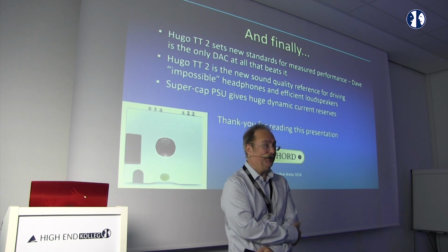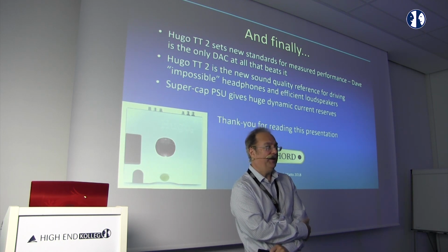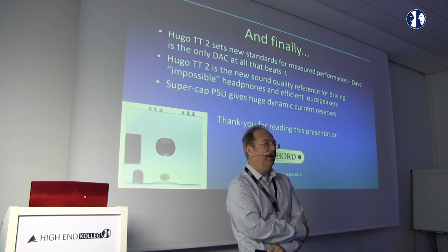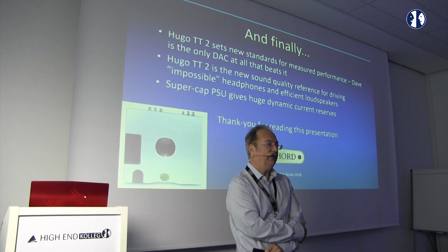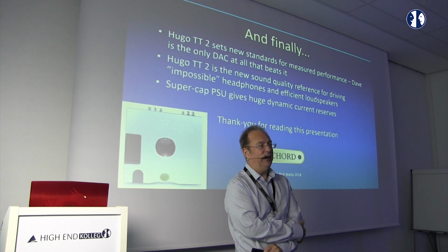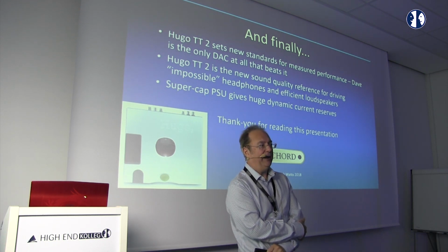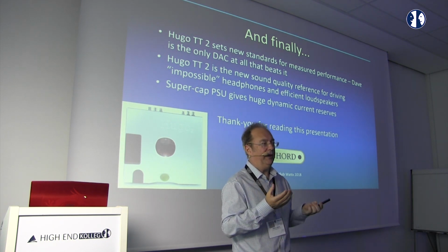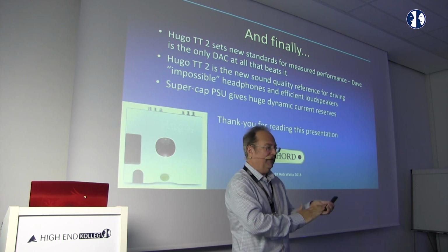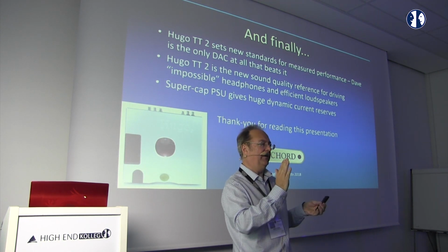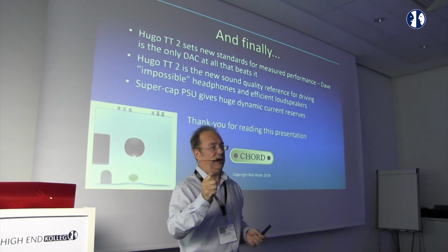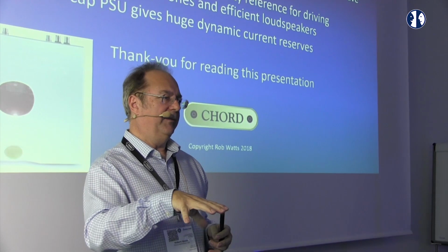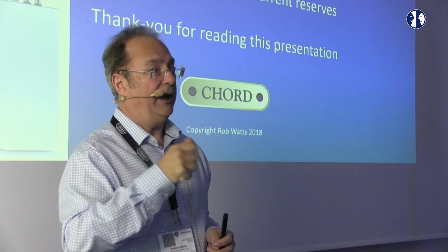Actually, the opposite is true. I find the best recordings are ones that were made in the 90s. Modern A to D converters are chock-a-block full of aliasing. They use half-band filters, and it's full of aliasing issues. What those do is stop the perception of that sharpness when you hit something hard. So if you're doing a rim shot on a drum kit, for example, it sounds very sharp. When you play that through a modern A to D converter, it sounds soft, unnaturally soft.